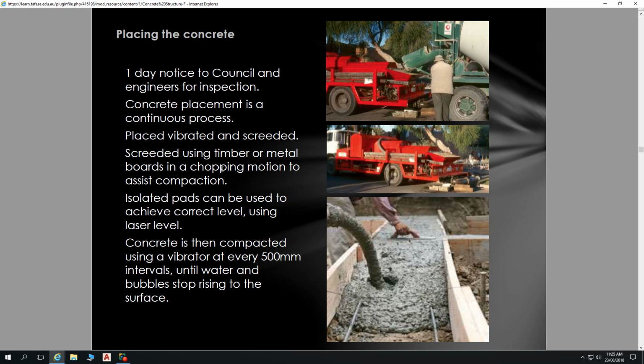When the concrete goes in, it has to be vibrated to ensure that all the aggregate, etc., settles properly. Now, that's not the result of poor vibration, but you get that same thing happening with poor vibration. The reason we've got that sample is that it doesn't have enough sand, cement, or enough of your fine aggregates in there to get around your coarse aggregate.